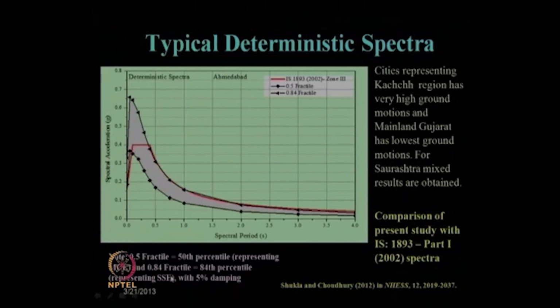That is what it means. And remember, this deterministic response spectra has been drawn with 5% damping of an equivalent single degree of freedom mass spring dashpot system.